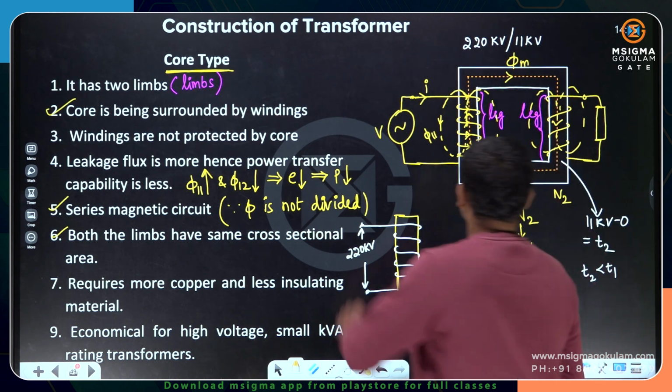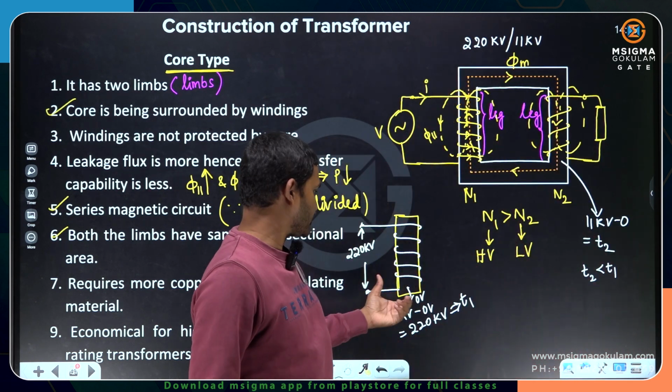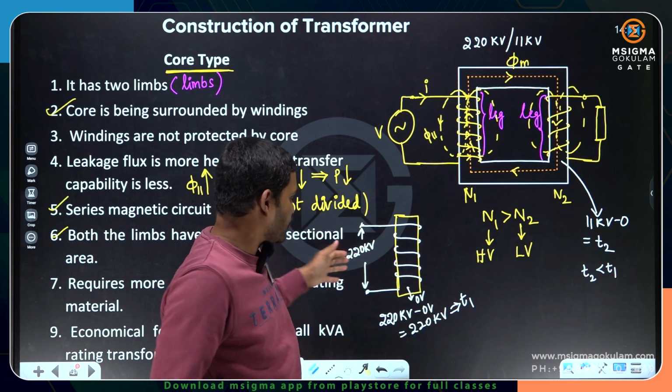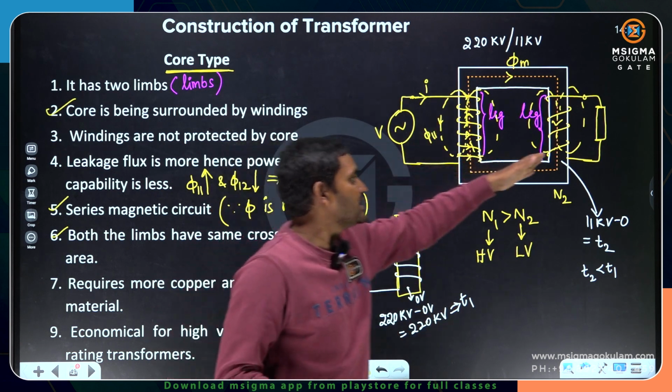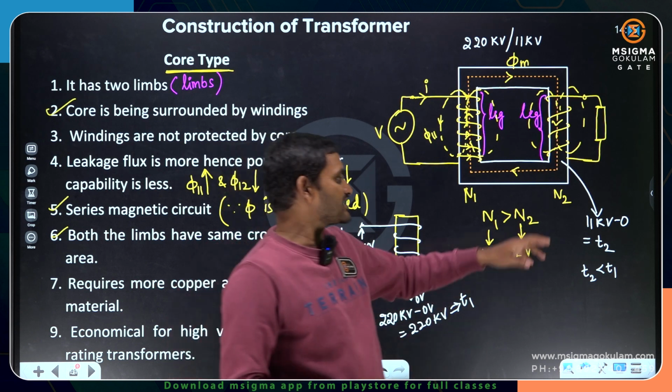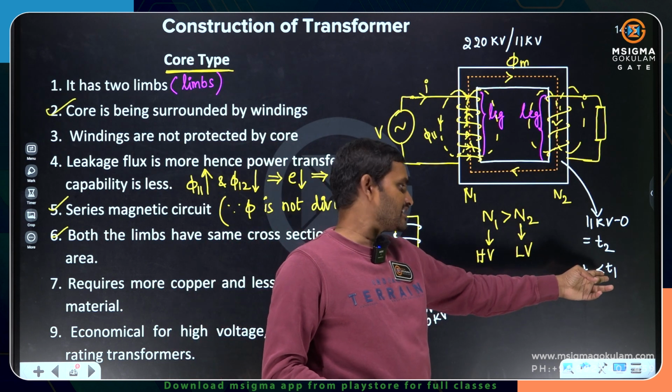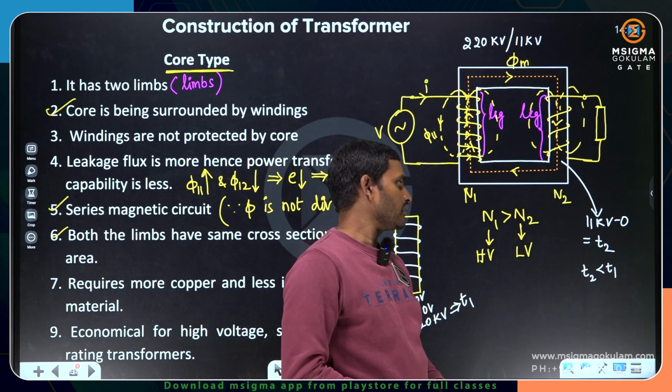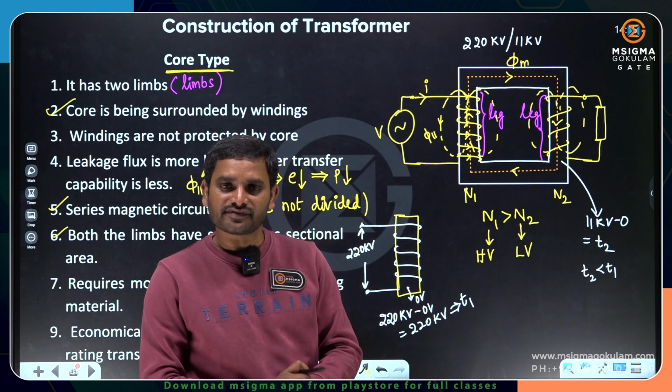because here more potential difference, more impressed voltage I can say, because more voltage I am applying on the high voltage side, less voltage is generated on this side. So to withstand less voltage, less thickness of insulation. Okay, to withstand more voltage, more thickness of insulation.